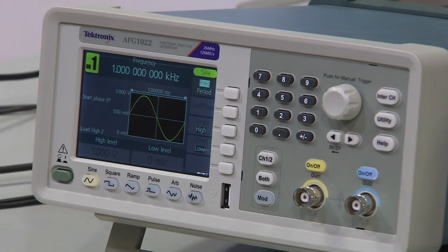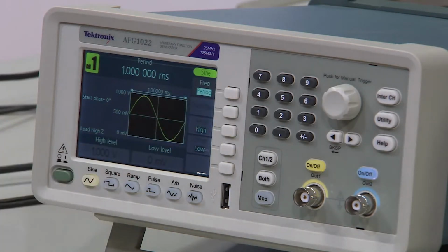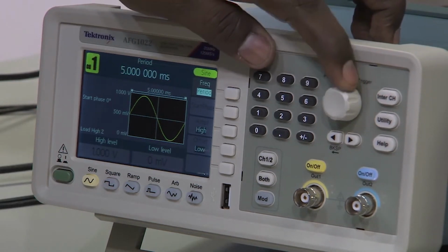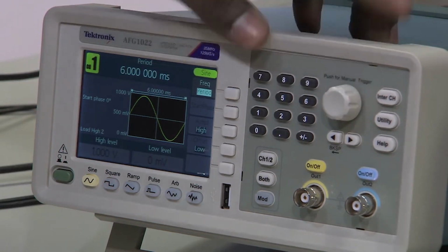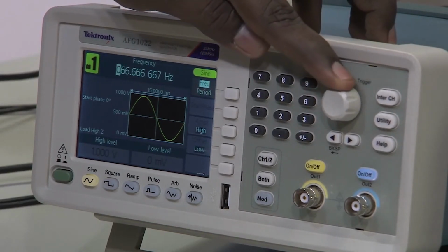So, there are several options on the side of this screen which are white color buttons, right. Each of those options is used to change the signal. Let us see the first one, which is the frequency and period. When we press the first button, first is your frequency and another one is your period. If you want to change your period, you can change the value again using the manual trigger knob, and in the same way if you want to change the frequency, again press the white button and you are back to the frequency mode, and again you can change the frequency.